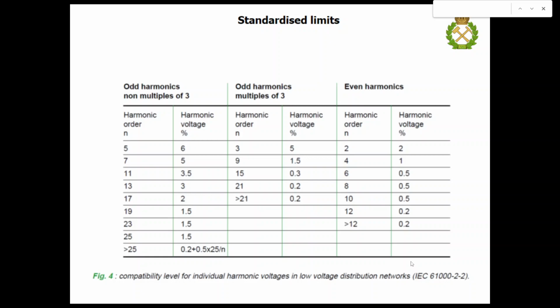And for each group of harmonics, for each number, you may see the harmonic voltage in percent of the fundamental component, and such limits can be used to maintain some technical devices to eliminate harmonics.